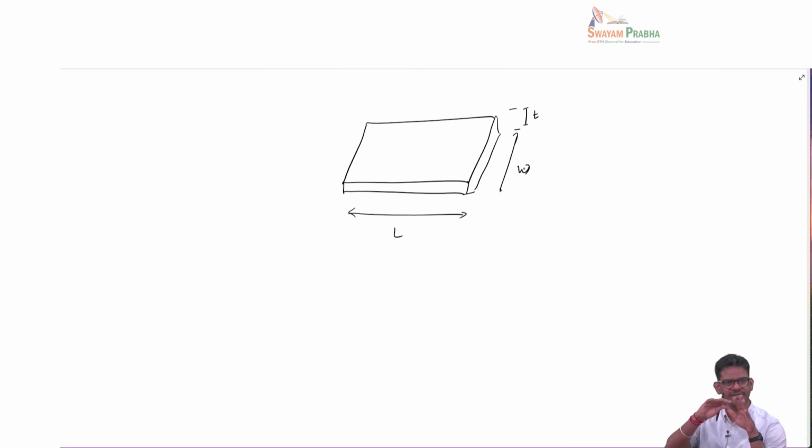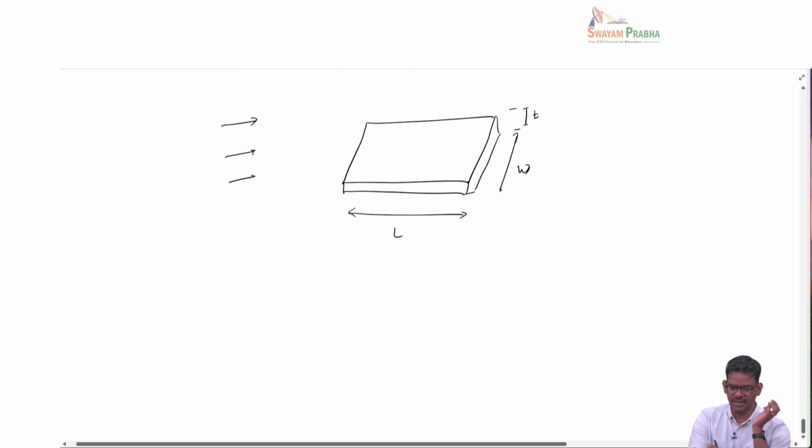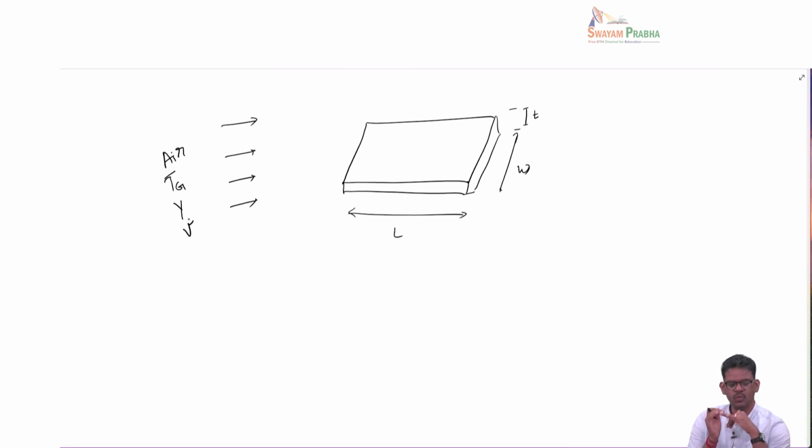The water forms a thin layer around the surface, and now I am going to send air for drying this. So this air is represented in terms of its dry bulb temperature Tg, that is the actual temperature, and it may have some initial humidity Y, and it will flow at a certain velocity v. These are all the characteristics, these are all the conditions for drying. When I fix Tg, Y, v, I say that this is a constant drying condition.